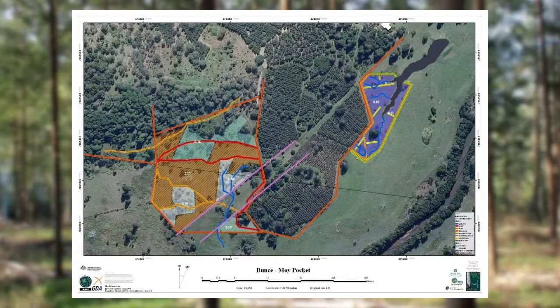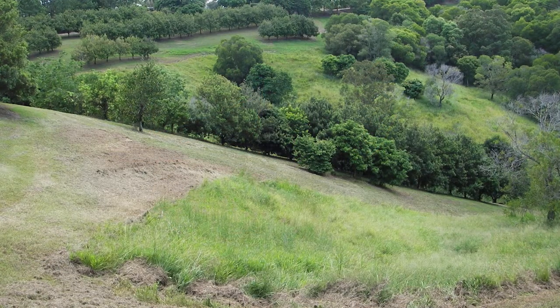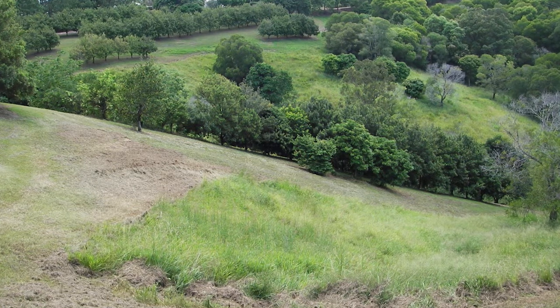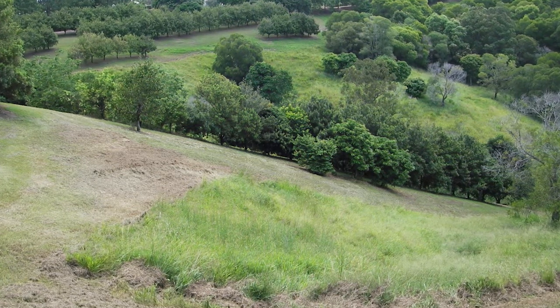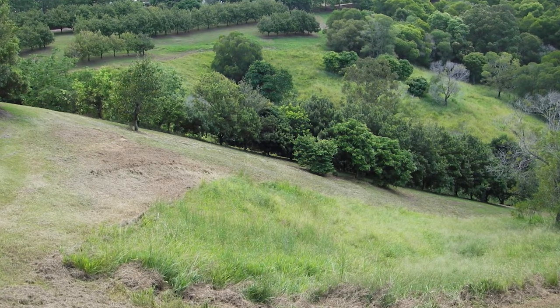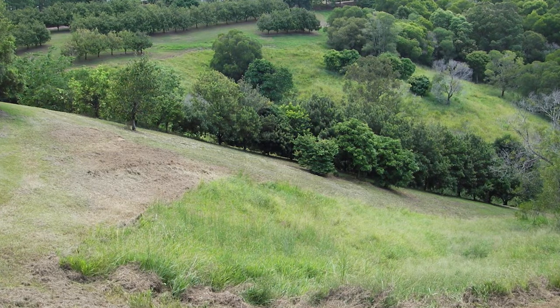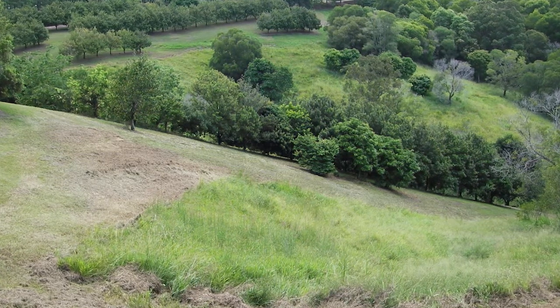A map detailing your infrastructure and plantation area will become a valuable tool when managing contractors. It's your operational plan and should be flexible, adapting to unforeseen issues that may arise during operations. The first operational process that you will undertake is the on-ground marking out of your plantation rows and infrastructure. That is, the design and layout of your plantation in relation to access, boundaries, remnant vegetation and slope.